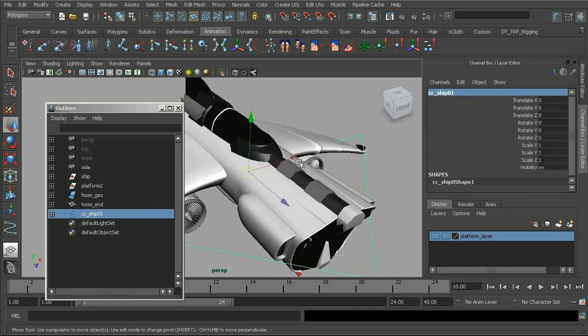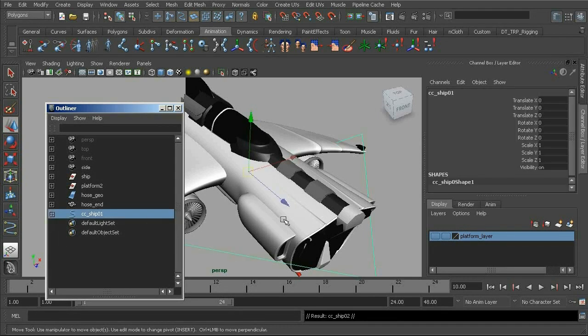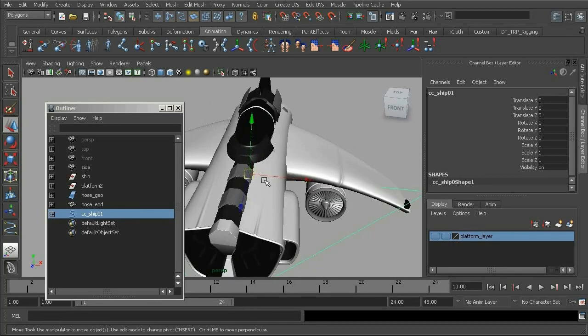The 01 makes it clear as to how many of these objects exist in this scene. If we were to ever duplicate this curve, which you can do with Control D, now we can see that there is another object of this type, and this basically means that we'd either need to remove the object or rename it if we decide to use it elsewhere for another asset. Alright, so I'll now go in and remove the object I've just duplicated. There we go.